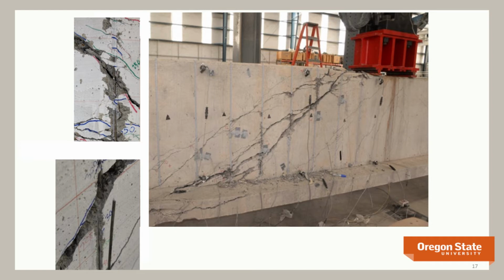All right, here's what our girder looks like after diagonal tension failure. The two pictures on the left are showing you that along that diagonal crack where we eventually have the failure plane, we're actually getting rupture of those titanium stirrups. Because of the mechanical anchorage combined with the chemical bonding along the length, we're actually able to make use of that high-strength material. So we fracture the titanium.